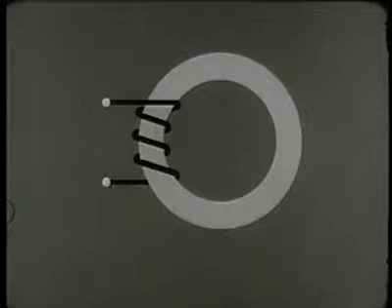To explain how cores store binary digits, we must know how they are constructed. Around the core is wrapped a conductor. Current flowing through the winding produces a magnetic field around the conductor. Because the core is made of highly permeable material, it forms a path for the magnetic lines of force.